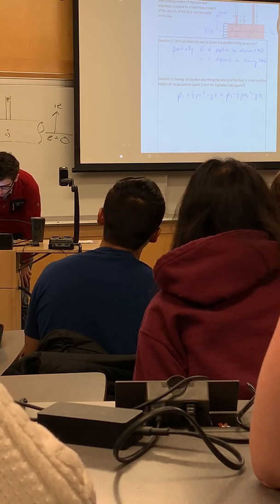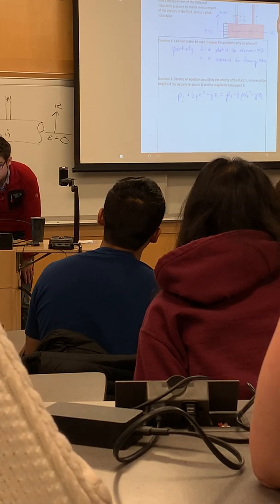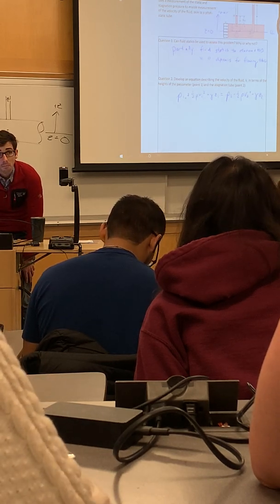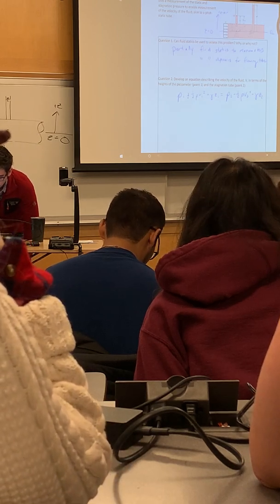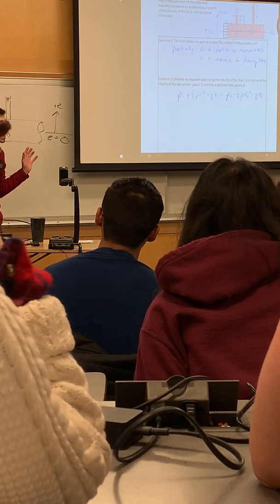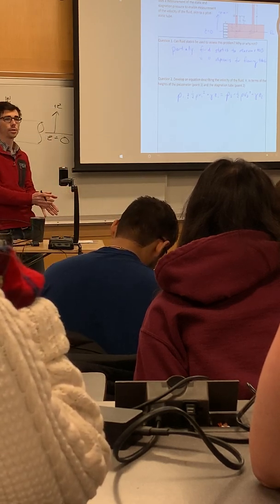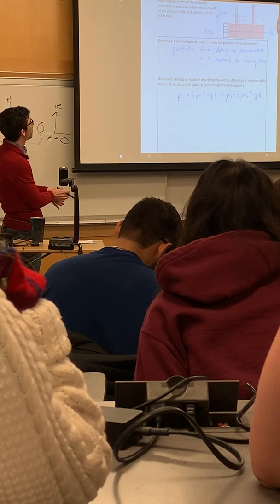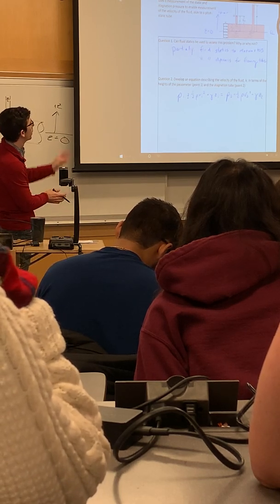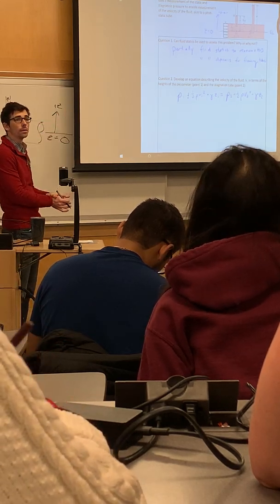What can we say about P1? Should we cancel it? Isn't it equal to P2? Is it equal to P2? No. So remember at P2, physically what's happening is we're taking all of that velocity and turning it into static pressure. Right? So that P term is embodied by the elevation of those vertical tubes overlying our points.